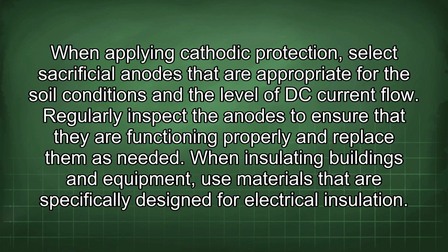When applying cathodic protection, select sacrificial anodes that are appropriate for the soil conditions and the level of DC current flow.